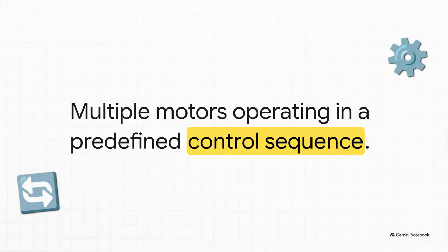Let's explore the sequential motor control project. Think of progressive stacking here. This project builds directly on that basic start-stop logic we just looked at, but now it choreographs a multi-step factory floor process. Just imagine a conveyor belt that absolutely cannot start until the shredder ahead of it is spinning at full speed. This ladder logic ensures multiple motors operate exactly according to that rigid, predefined sequence.